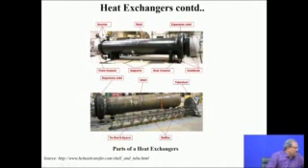This outer one is the shell, and since a significant change in temperature, increase or decrease, is associated, you need to provide an expansion joint to absorb the change in length, and there are some vents or drains which are added. Since the heat exchanger is going to be big and large, a lot of liquid will flow through it. So, there will be significant weight, and it needs to be supported appropriately on the factory floor. So, this is just a picture of how it would look like.